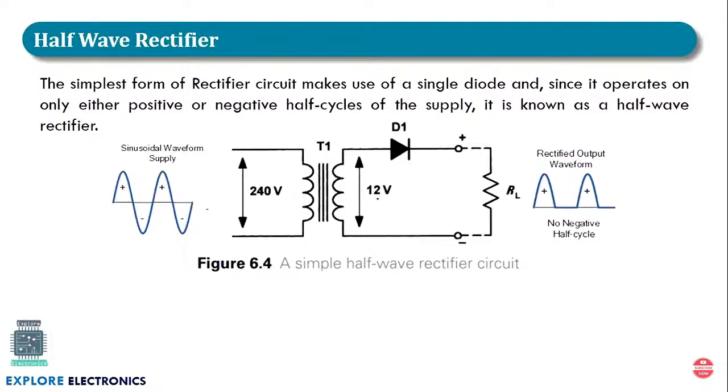And we are connecting that to the diode D1. As we know, diode D1 conducts when it is forward biased and diode D1 is off, or not conducting, when it is reverse biased. So we will be having a load here, that is RL. We need to observe the voltage across RL so that we can observe the voltage generated from the rectifier.